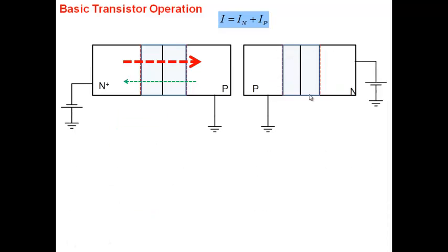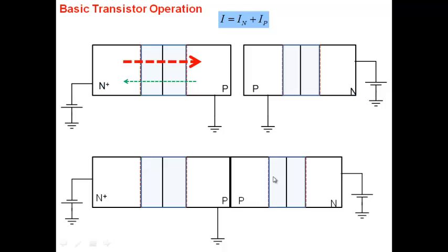Alright, so now what we're going to do is take these two PN junctions and fuse them together. The two junctions are taken and fused together here. Now, look at what happens here. This junction is still forward biased. Electrons are being injected here. Now, these two regions are connected. There's one single P region here. Forget about this line anymore. There's no line. One single P region here.